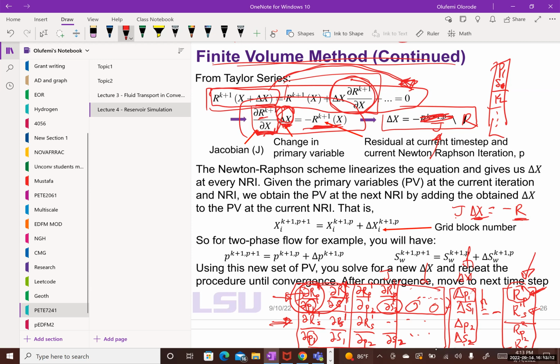If you try to program that logic, you will see it's a lot of pain to do based on the perturbation method. Yes, there is some non-local indexing that you will come up with to figure out which are zeros and which are not, based on the grid. The grid can be unstructured because this is finite volume you're looking at. That's why it's complicated. If it's Cartesian, regular grids, you already know the neighbors, east, west, north, south, and then you can program and perturb only that. That one is easy.